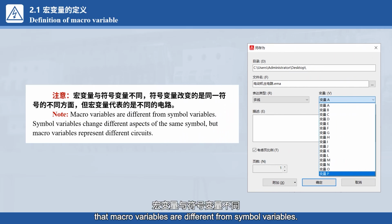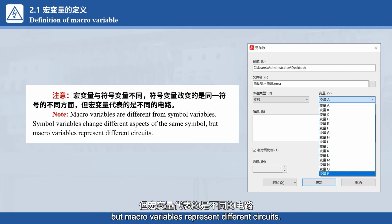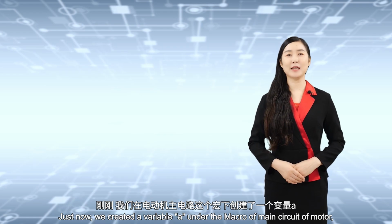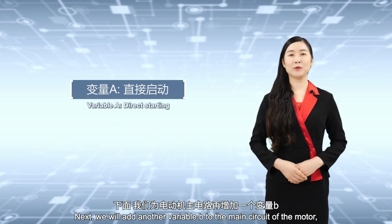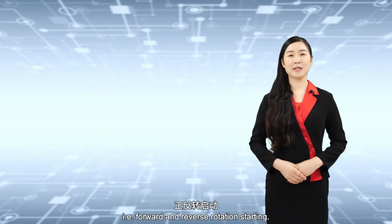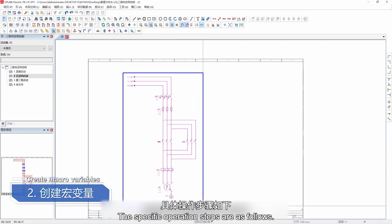It should be noted that macro variables are different from symbol variables. Symbol variables change different aspects of the same symbol, but macro variables represent different circuits. Just now, we created a variable, A, under the macro of main circuit of motor, that is, direct starting. Next, we will add another variable, B, to the main circuit of motor, that is, forward and reverse rotation starting. The specific operation steps are as follows.